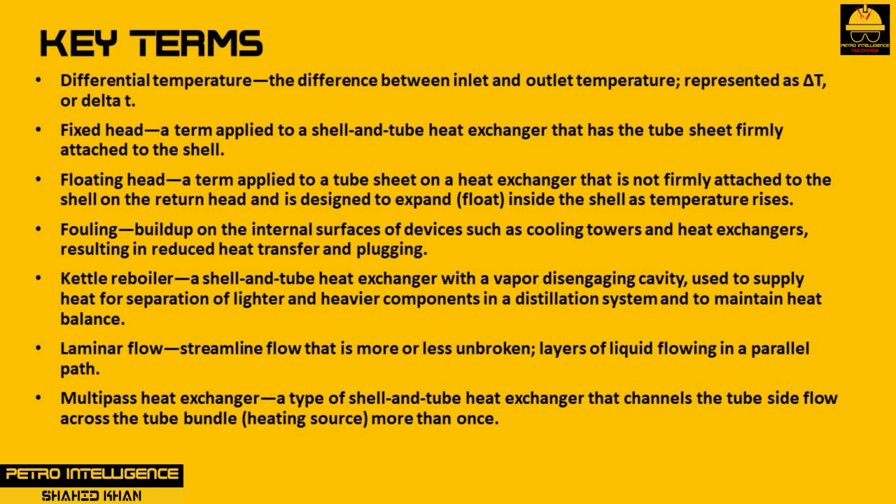Fixed head is a term applied to a shell and tube heat exchanger that has the tube sheet firmly attached to the shell. Floating head is a term applied to a tube sheet on a heat exchanger that is not firmly attached to the shell on the return head and is designed to expand or float inside the shell as temperature rises. Fouling is buildup on the internal surfaces of devices such as cooling towers and heat exchangers, resulting in reduced heat transfer and plugging.